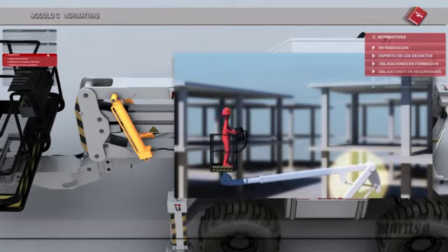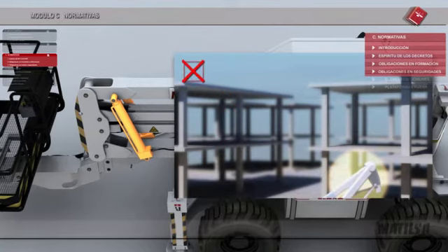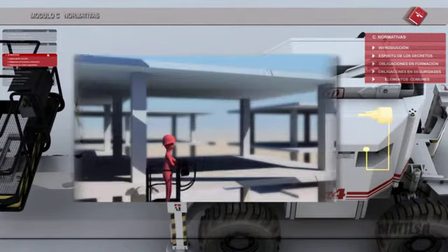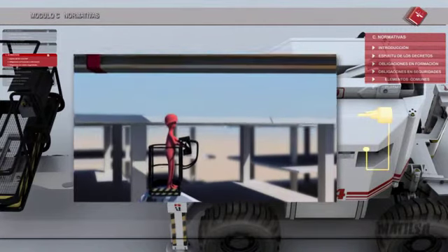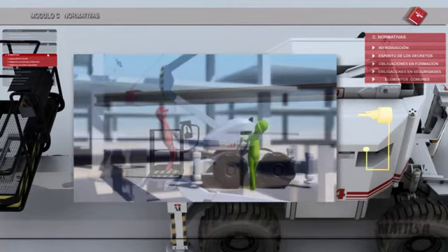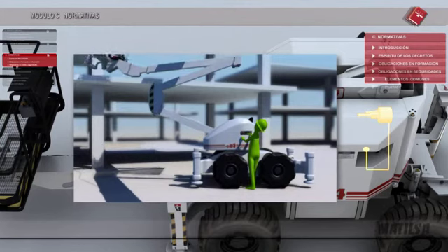The safety valves must always be located next to the hydraulic cylinder. Emergency lowering manual pump. Several different models may be found, their location and lowering systems depending on the manufacturer. The most frequent, and at the same time compulsory, is on the base of the machine. This makes it easy for the operator to remove anyone who has suffered an accident by using the controls situated on the base of the platform.